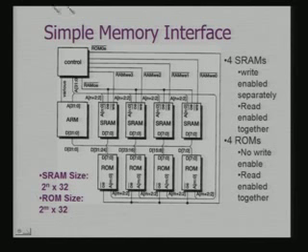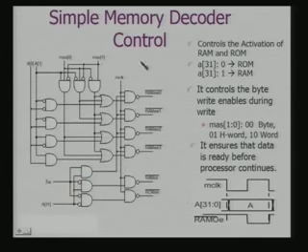Now, the next question comes: how do you design this control? When I am designing this control, what do I have to do? I have to use various control signals which this ARM core is producing, okay, and those control signals have to be used. So, this is a simple example of a control signal. Now, this control can be implemented on an FPGA or may be implemented in terms of discrete logic. If it is really going into an SOC, this becomes part of the SOC.